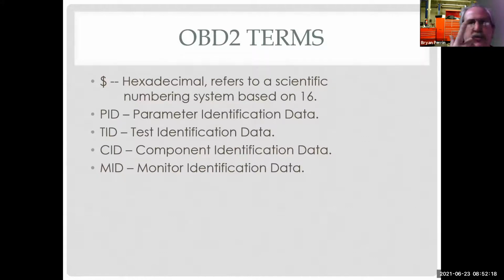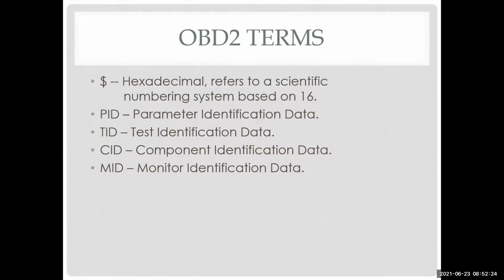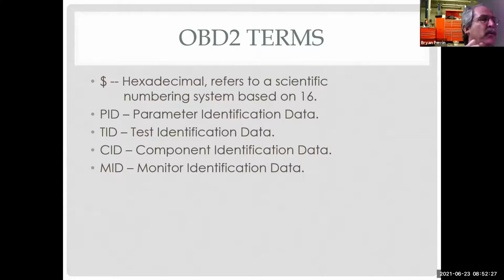Those are our addresses, what the scan tool is using without our knowledge. However, when we look at mode 6 data, we will actually use TID, SID, and MID as part of interpreting our mode 6 data or looking it up. So these are things we'll actually see.